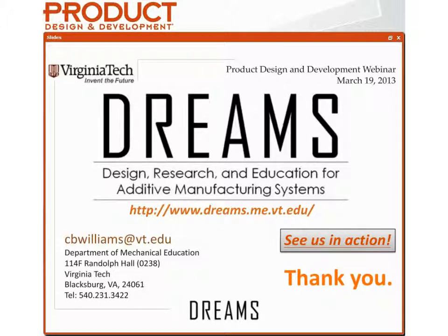With FDM, the layer thickness is a little bit thicker, so you're not going to get as smooth surfaces. So it's tough to quantify what the ultimate capabilities are, but I can tell you that there are plenty of people who use parts printed off a PolyJet machine as patterns in a molding situation, as Chris referenced in his presentation, and folks that have used FDM parts in a real production environment. So it really depends on what your needs are. Chris, I don't know if you have things you want to add to that.